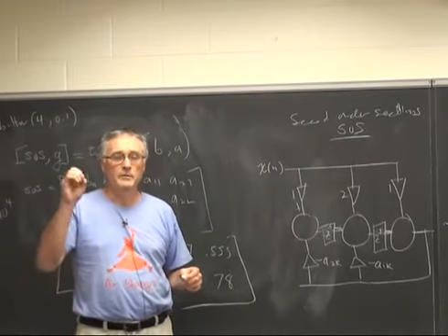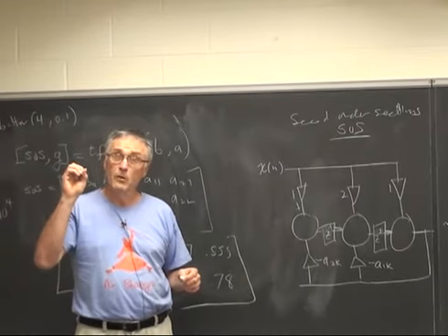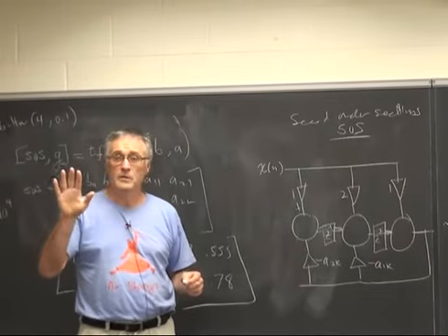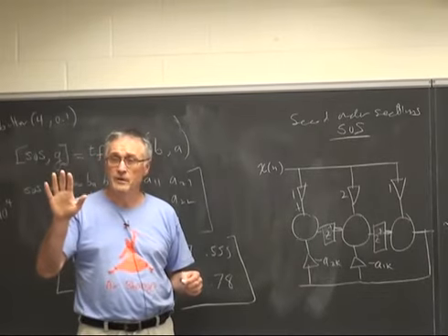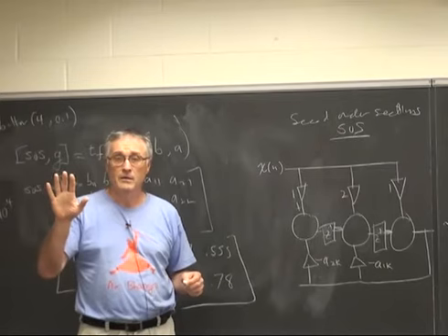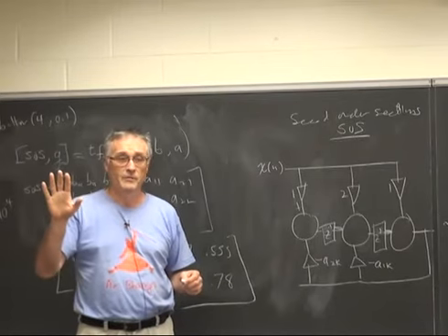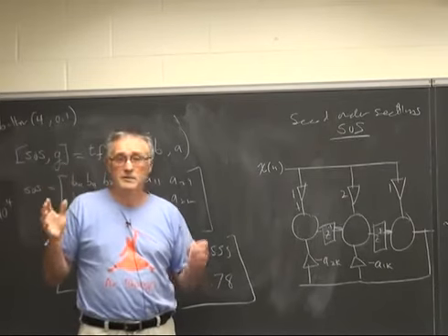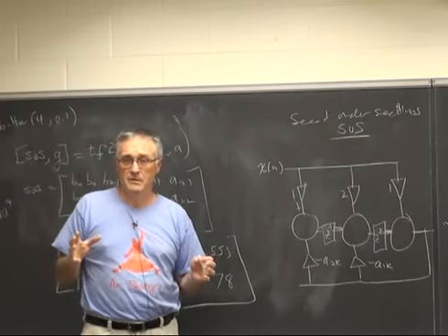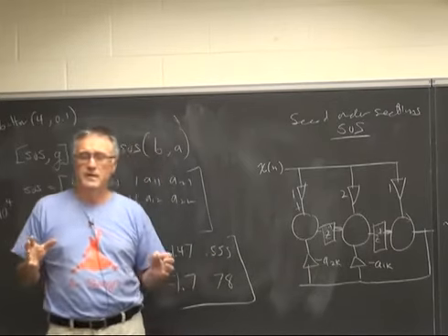You can implement about 1 second order section on this chip before you run out of hardware if you use IEEE floating point, because it's monstrous, right? You might be able to do 2 second order sections.